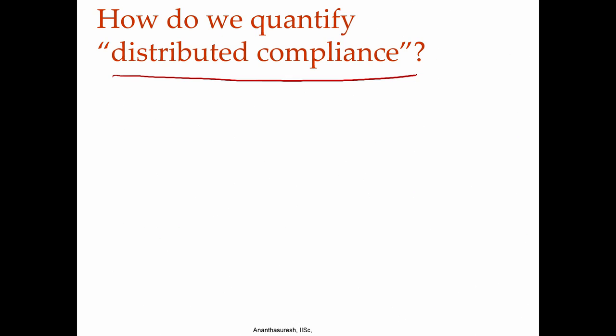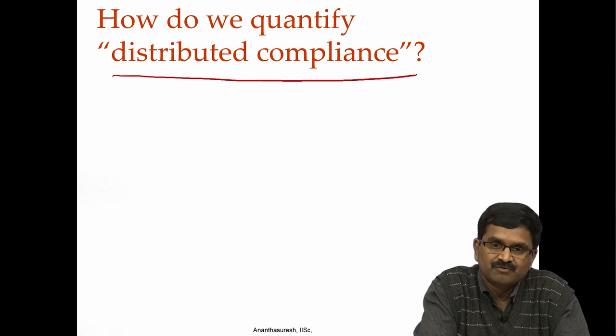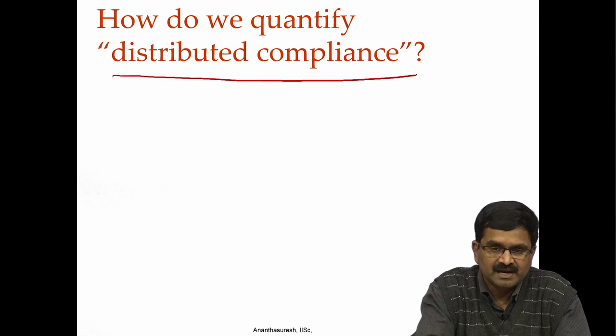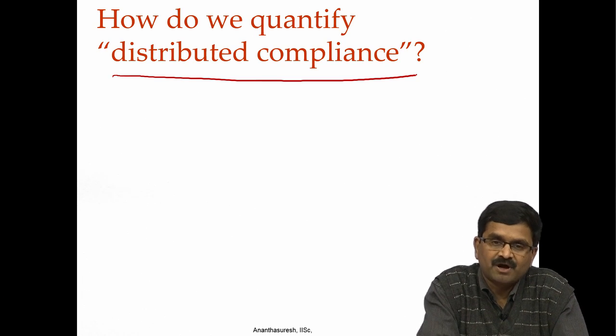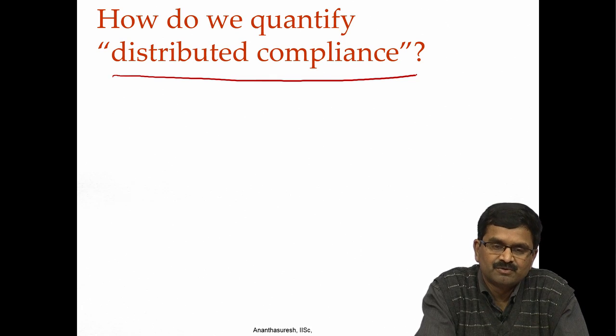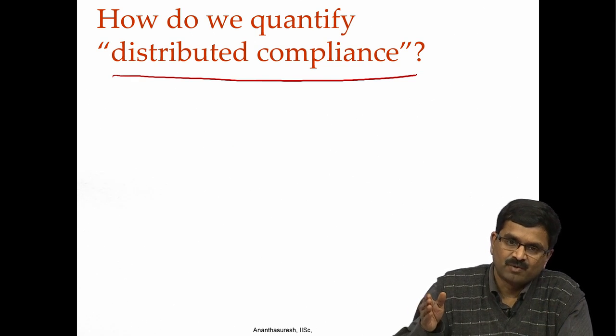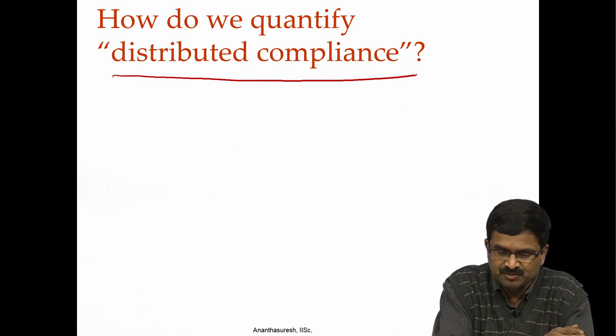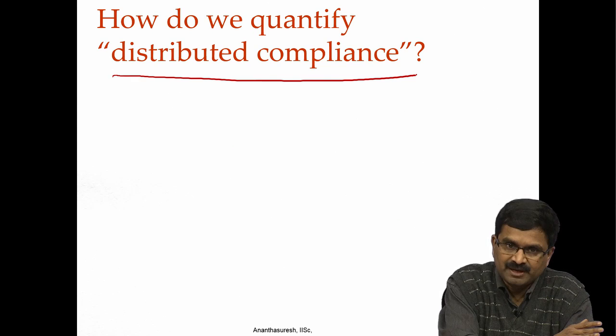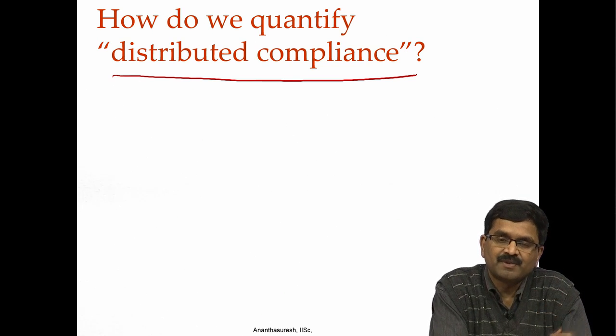But what do you call a distributed compliant mechanism? Is it the one where elastic deformation is uniformly distributed? Yes, in words that is what it means. We have to have the elastic deformation happening throughout the structure, but how does it happen? Is it possible at all to come up with a criterion, a quantitative measure, that says that this mechanism is this much distributed compliant, as opposed to discrete? If we put some spectrum, one end is discrete, the other end is distributed fully uniformly everywhere. Is that really possible, to have a compliant mechanism where the stress is the same throughout?